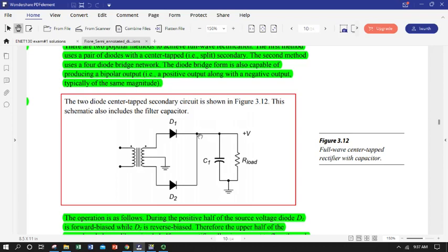We get to this node, and at this point our conventional current has a choice. We have a parallel circuit here, a node, so it can either flow on to our output circuit, or it can flow down here and through this other diode. And because it's conventional current, it's positive current flow, it's not going to go through this diode. So this diode's going to act like an open, so it's not going to go down this vertical branch. It's going to continue on to our output circuit, and it is going to simultaneously charge our smoothing capacitor and drop over our load.